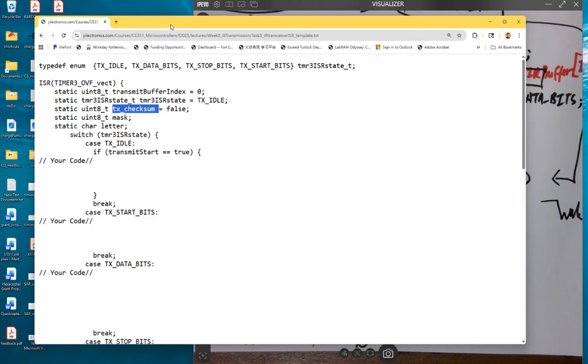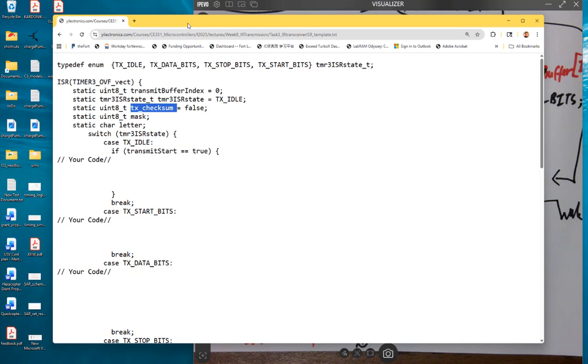And also something else to let you know. I'm not expecting your board to be significantly larger than our Skyboard. The free Eagle version has a restriction on the size of the board. I think it's 10 centimeters by 10 centimeters as a limitation. So if you want to make a bigger board, you still have to use Fusion 360.